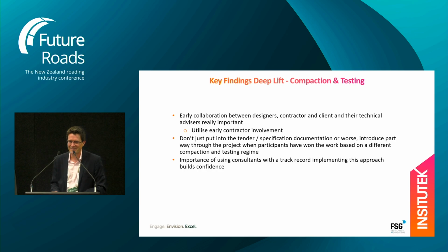Yeah, interesting stuff. Just on your number of passes, I'd be a bit suspect about where the number of passes actually achieves compaction. I like your stiffness test, that's good, but maybe for asphalts, yes, but in pavements, I'd be a bit suspect. So the way that the number of passes is come up with is you will do trials.